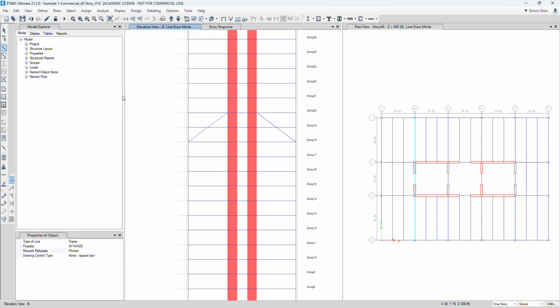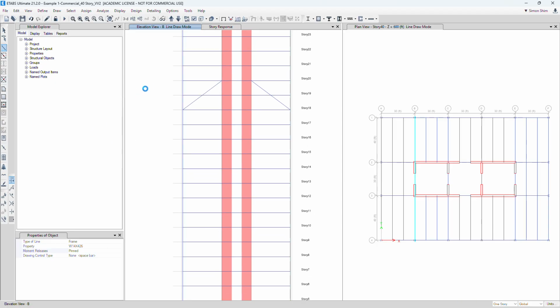But now when we tie these columns together, they are going to take lateral wind load too. We will show you. So in order to make the outrigger system work, you need to increase the significant section size here, and this truss is going to be a very heavy section. So most likely you are using a big section with your strong arms. Basically, you are adding lateral stiffness.